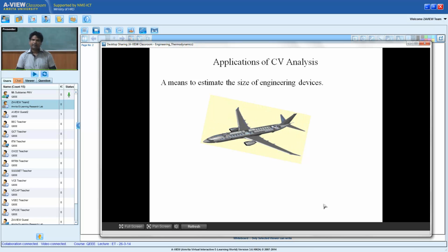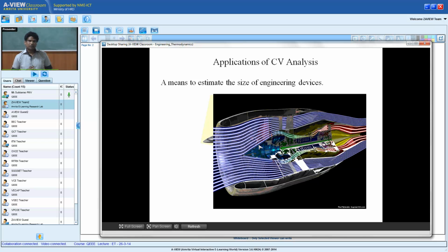Now let us say there is an aircraft which took off and reached the cruising altitude, generally 10 kilometers plus. After reaching 10 kilometers, almost all aircraft travel with a constant speed. Nothing will change. Now, all of you know there is an engine attached to the wing. If you look closely, this engine is able to produce the entire force required to move, consuming a lot of fuel. Continuously, air enters by virtue of relative velocity, and this air is subjected to many thermodynamic operations because there are a series of control volumes inside, and finally what comes out is a high velocity, high temperature jet.